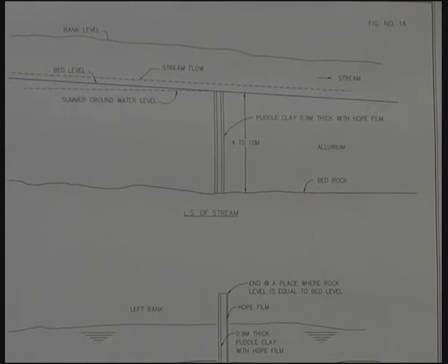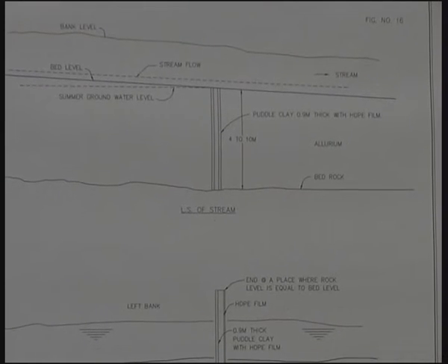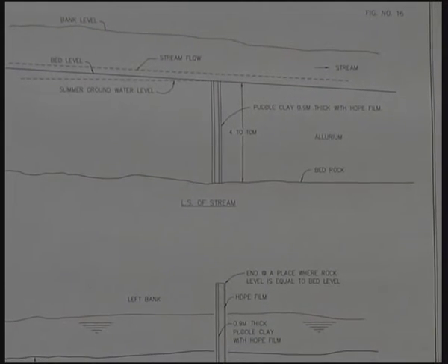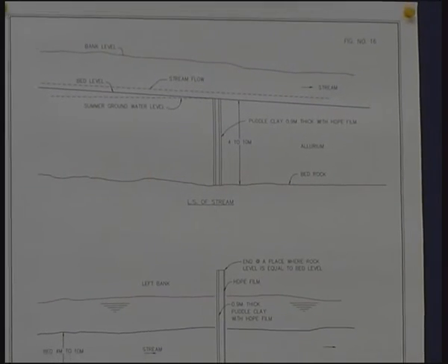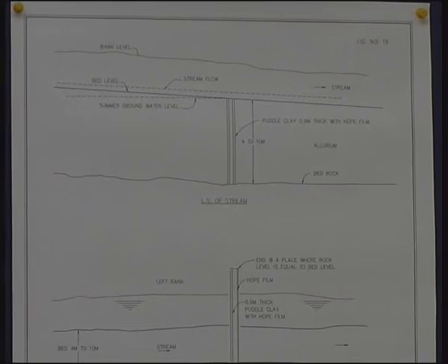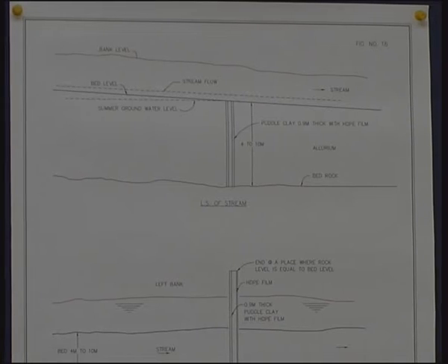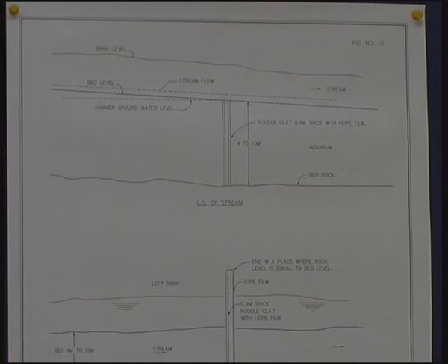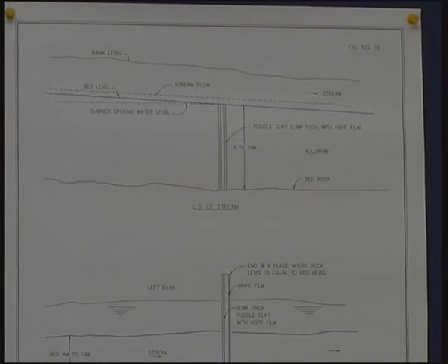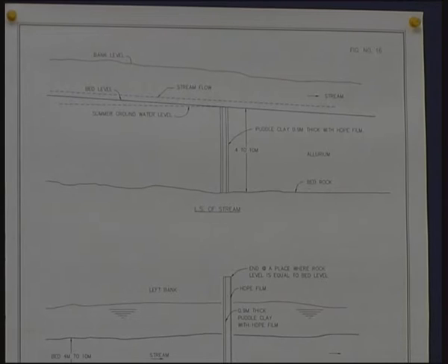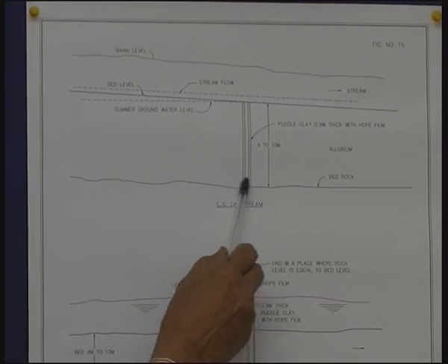It has to be collected from a nearby tank, an old tank, at a distance close to the bund where puddle clay is available, and it has to be brought to the site, and after making that into powder, water has to be added into that, and lumps of puddle clay will have to be carried through manual labor and dumped on the bottom layer.